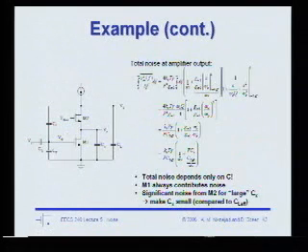So here is the total output noise. Total output noise is KT over CL times a gamma over F times an extra factor. And this extra factor we know is due to the cascode transistor. So without doing any math, just remembering this one result, we can very quickly verify this result is right.